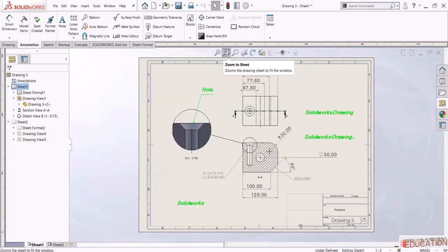So there's a link between the 3D model and this sheet. Now, when you export it to another format like PDF or DWG, DXF, this link will be broken. So you need to keep the original model. You can delete it, because when you delete the original model, the relationship or the link between them will be broken, and then you will not be able to view this drawing. Before exporting, I'll need to delete these notes here.